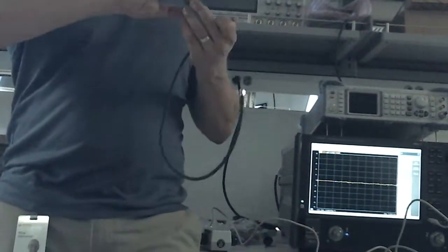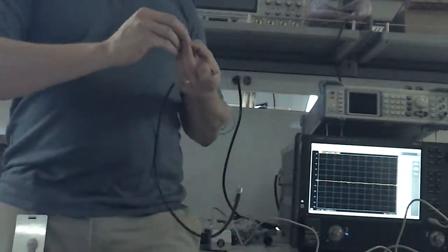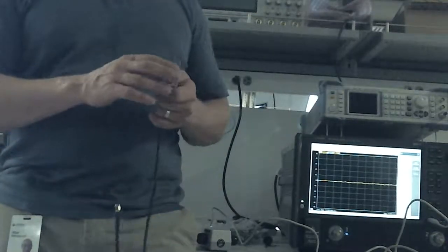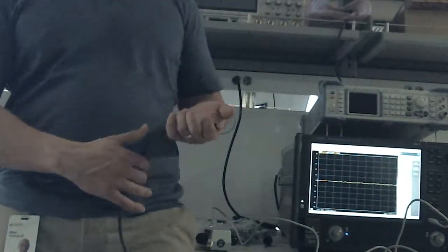This is part of the shielding. It's meant to take mechanical stress. That's why the thread is here. If I rotate the whole cable or the female adapter as a whole, I'm putting mechanical stress on the inner conductor. That's where the RF signal goes. That's no good, right? So I always want to rotate the male outer nut.